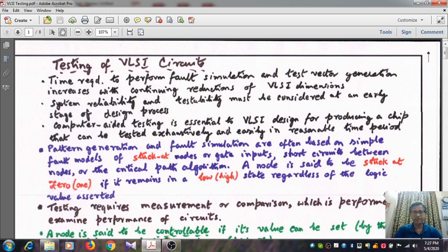Say, for example, for a gate input of an NMOS transistor, suppose there is a disconnection between the metal conductor and the polysilicon gate. Then even if we make the gate voltage high with respect to source, the transistor will never be able to come on. So we say that in this circumstance the transistor is stuck at 0.